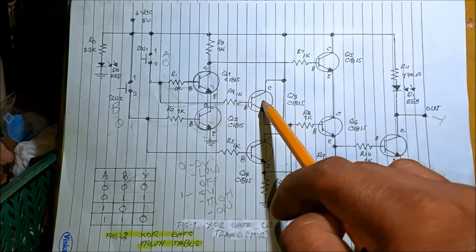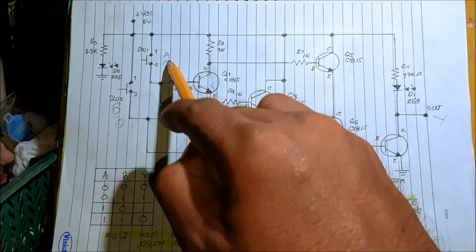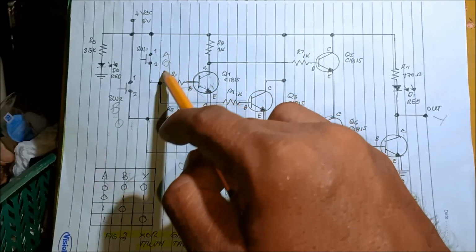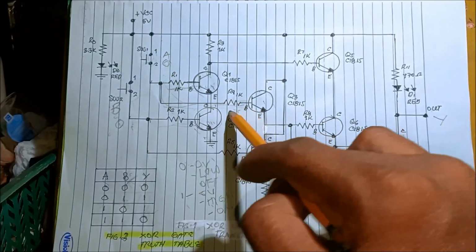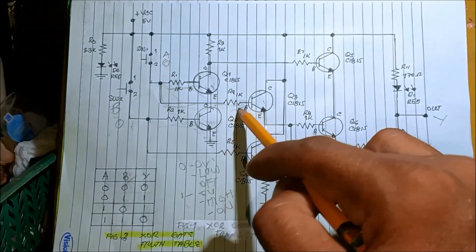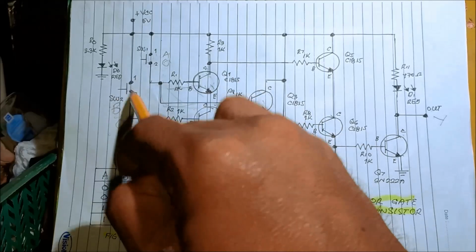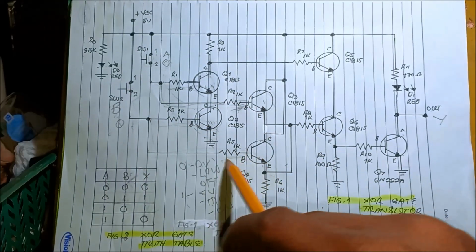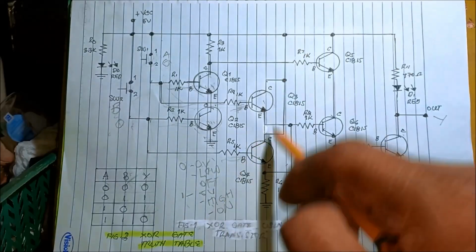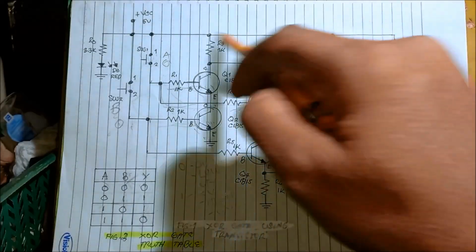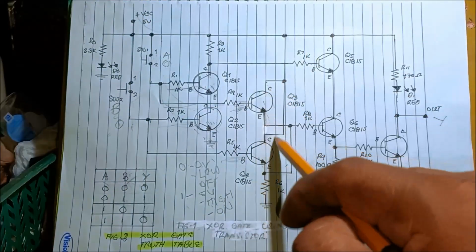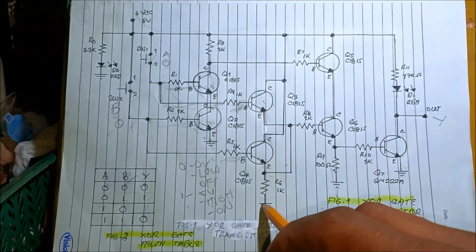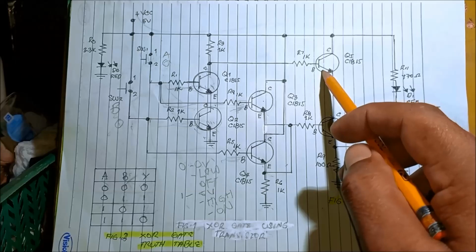How about this transistor? Since this is 0 level, or off, low, there's no base current. This is also off. Since the switch is open, this is also off. There's no base current to turn this transistor on, from the source through the collector and emitter to the ground. How about this transistor?